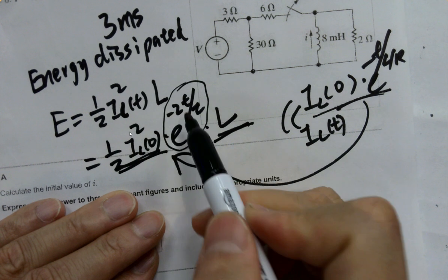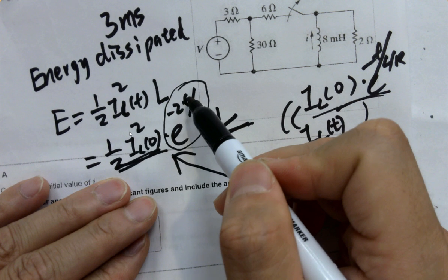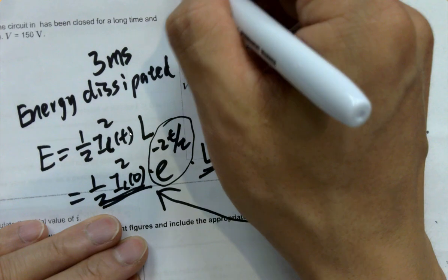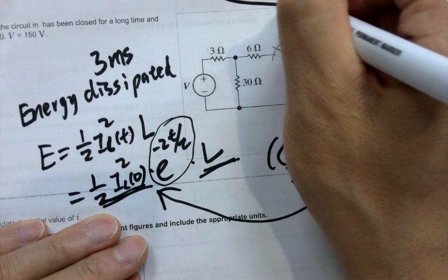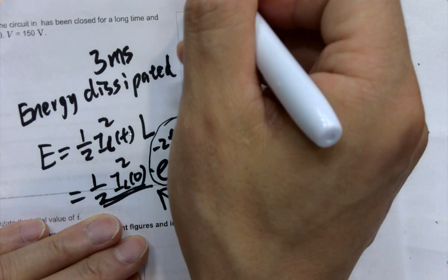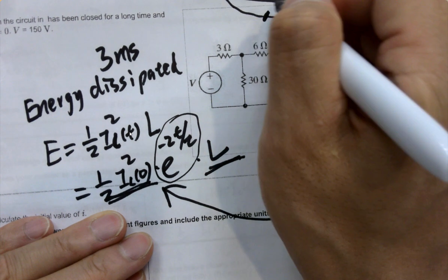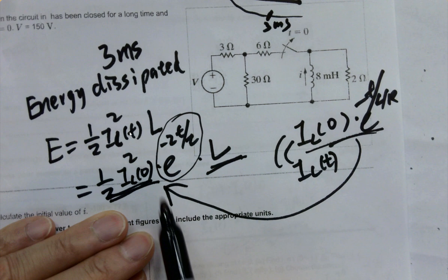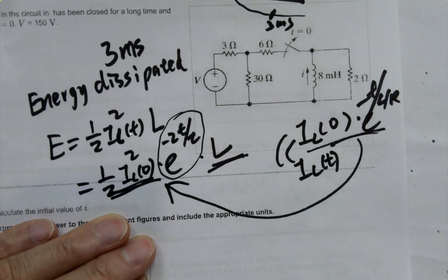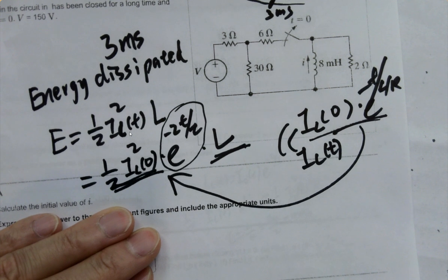Right? So that's the energy stored in there if you plug in 3 milliseconds. It's attenuating over time because there's the I0 at the very beginning, and the current is attenuating. So the energy is attenuating this way, probably more aggressively, but in a similar way. Eventually when it reaches 3 milliseconds, you can find out what's the current energy in there. So 1 minus it will be the energy already consumed by the resistor. Make sense? Because this is less than 1.